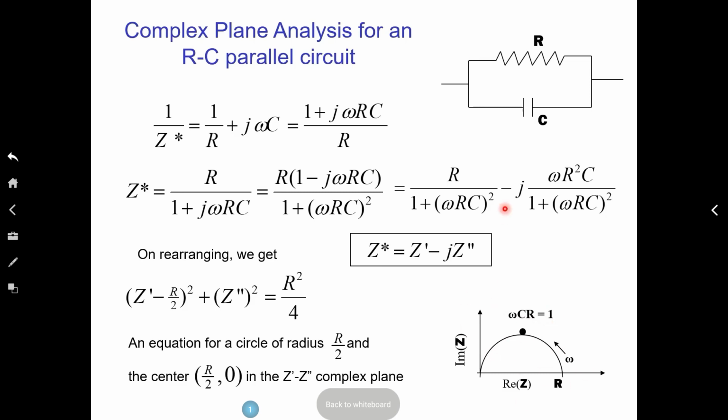What are we doing by doing this circuit analysis and this so-called impedance spectroscopy? We are getting numerical values for the circuit elements that we're using to describe our material. For a simple single phase, maybe single crystal material, this can be the resistance of your sample and the capacitance of it.